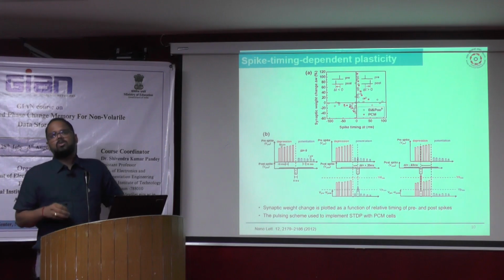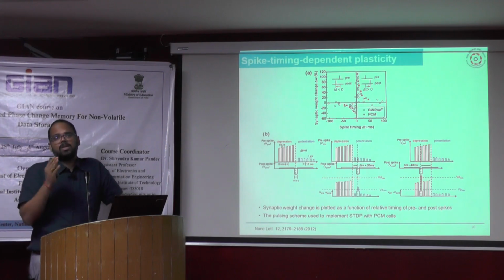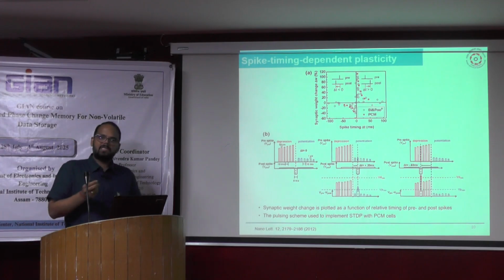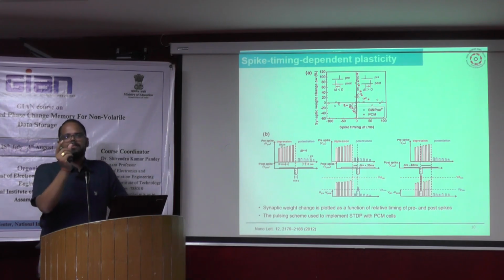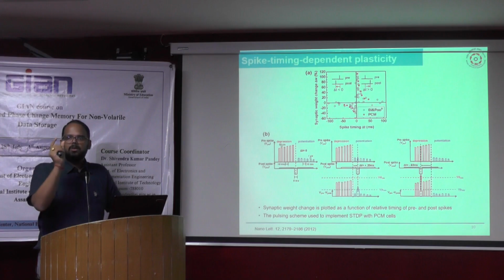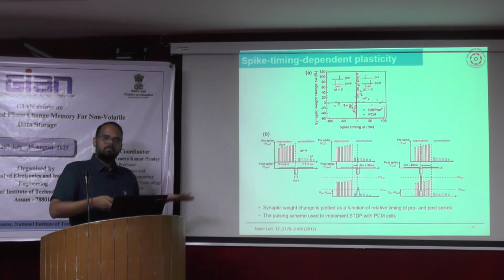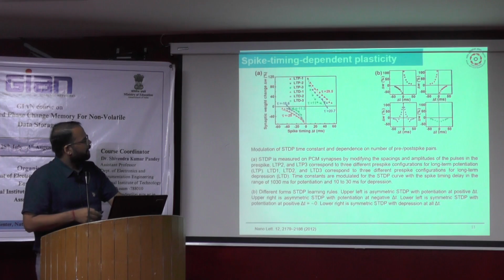This is the pulse. For that, you need to experimentally optimize the electrical pulse using your waveform generator or parameter analyzer with respect to pulse width and magnitude. So for experimental work, when we are able to fabricate the device, we need to optimize our electrical pulse using a parameter analyzer or arbitrary waveform generator, study the conductance change, and identify this behavior.